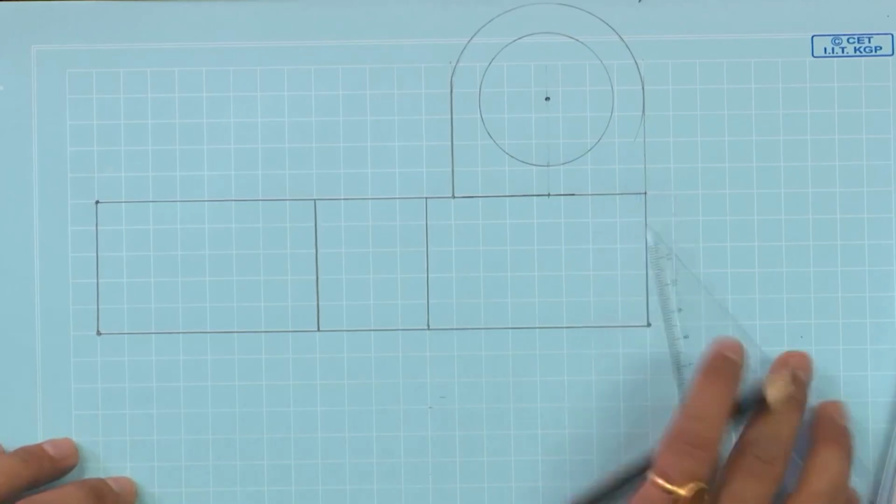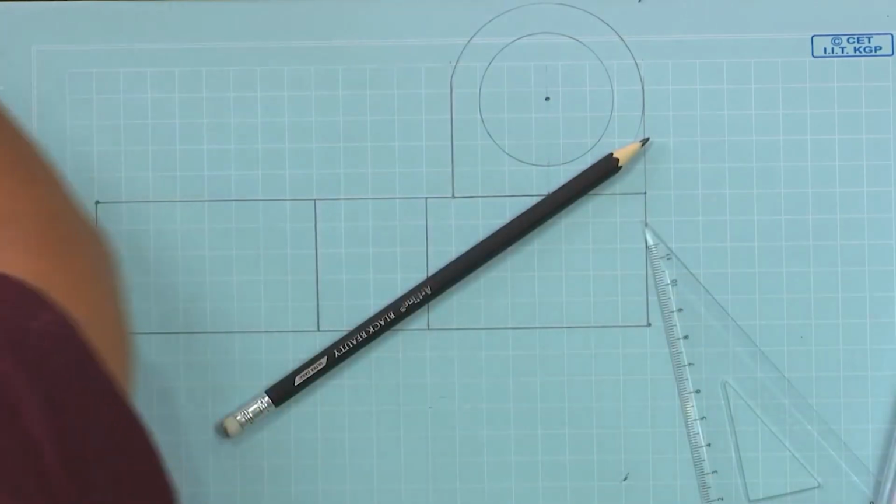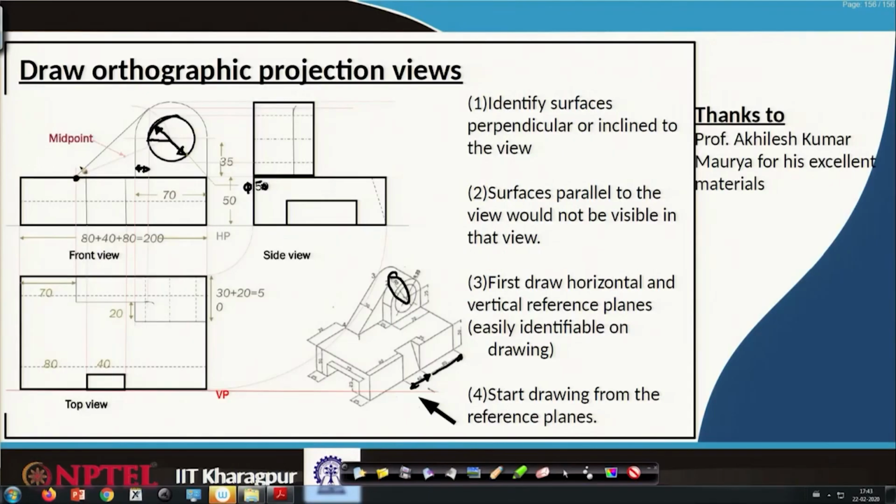At 70 mm we have to locate a point, for example, let us look at this picture. There is a point there which is at a certain distance from here to there, that is 70 mm. We already know this part, we have that inclined cut going by 70 mm. So, first locate a point, then we have to construct a tangent from this point to that circle. So, recall from an external point how to construct a tangent.